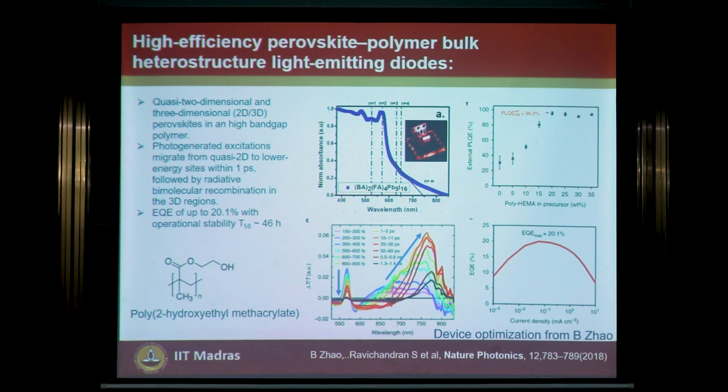When we do spin coat, it self-assembles in all possible random directions. It can be C-axis, face on or edge on, we don't know. You can control that also depending on the solvent you use, whether the solvent is very volatile or slow. It's all a self-assembly process. But yet we can get good numbers. For example, the EQE, when the device has been optimized, we could get an EQE of quite 20%, which is pretty much one of the high numbers for solution processed LEDs.